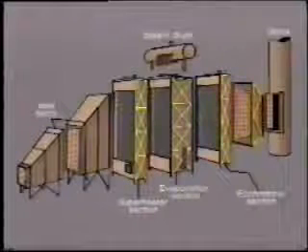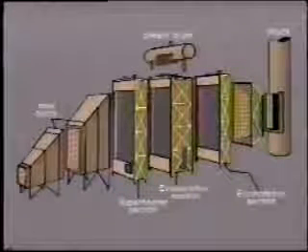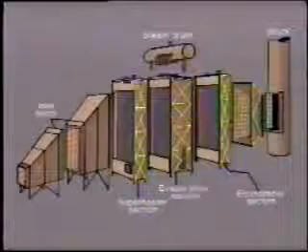Here we see the basic construction layout of a natural circulation HRSG showing the major components. The inlet duct is carrying gas from the gas turbine exhaust at temperatures as high as 1,100 degrees Fahrenheit or 600 degrees Celsius. For this reason, the steel casing must be well insulated so as to avoid heat loss to atmosphere.